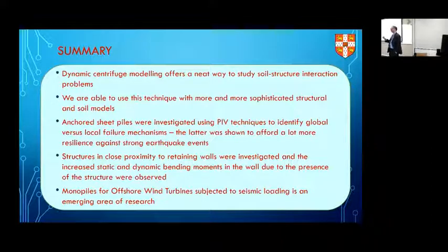The damping is one of the important things, and going back to Abir and my PhD time, long time ago, one of the early things we worried about is the amount of radiation damping. And what we found was that when you're dealing with soil, the material damping is the biggest proportion compared to radiation damping and any structural damping.